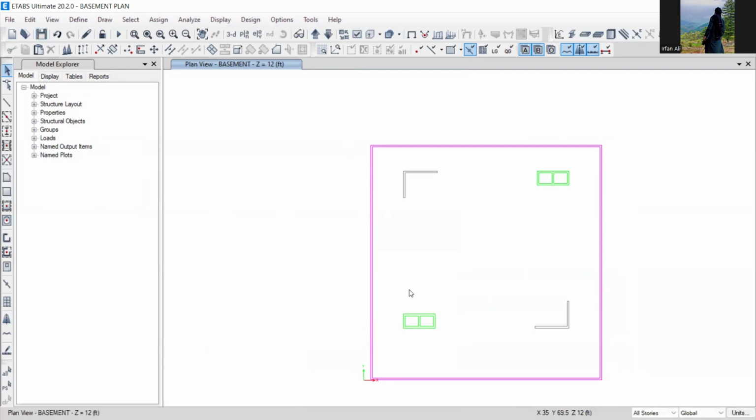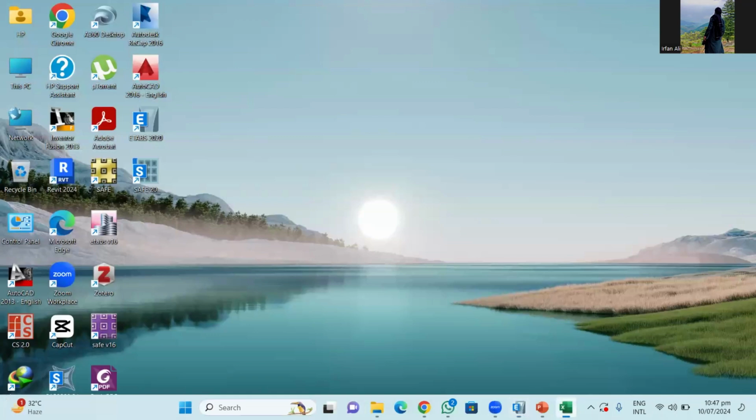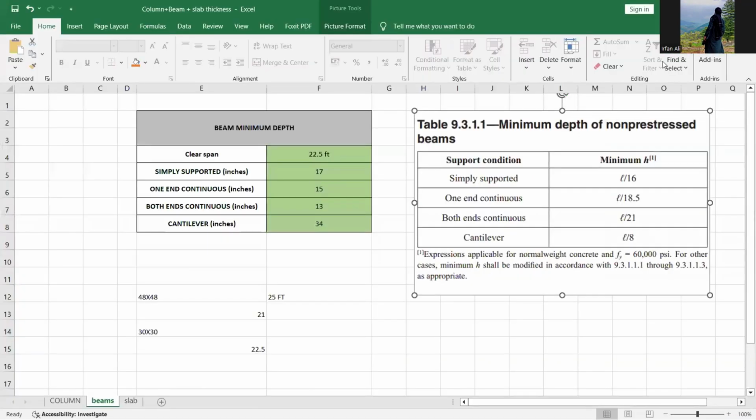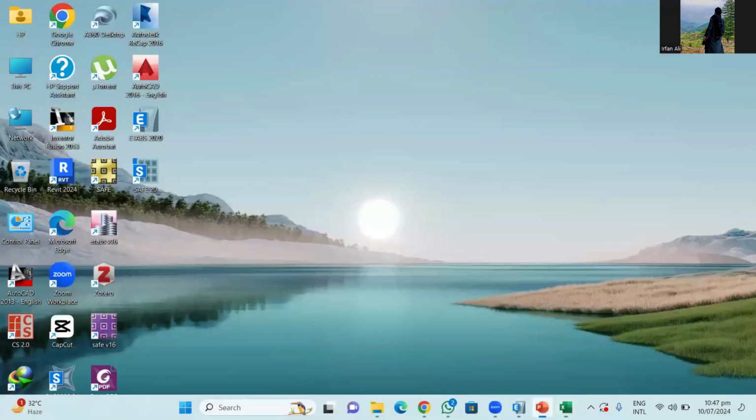You can also decrease the f'c of the shear walls and lift walls when you are designing only a moment frame. But in the dual system, it is advisable not to change the f'c. So this is done.